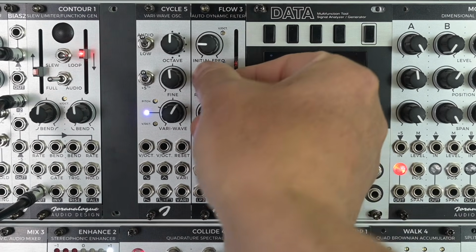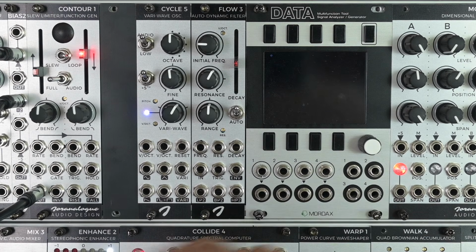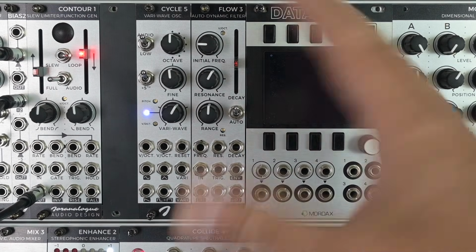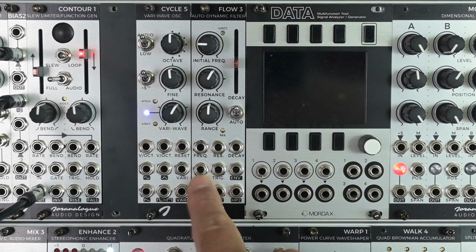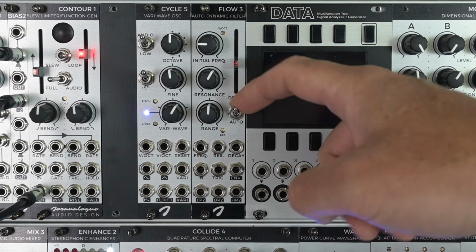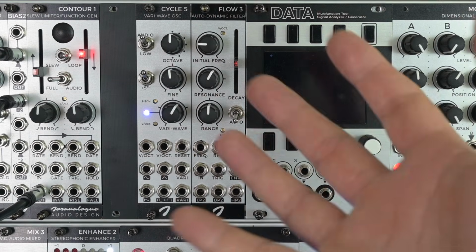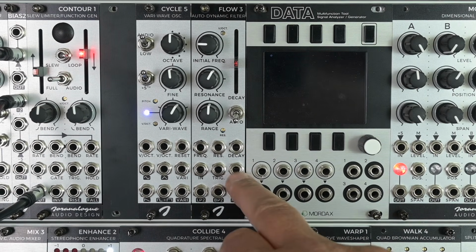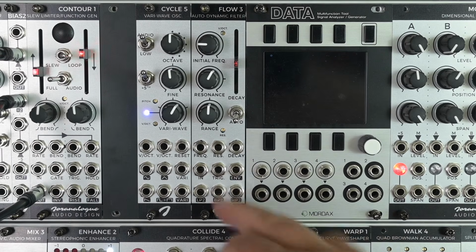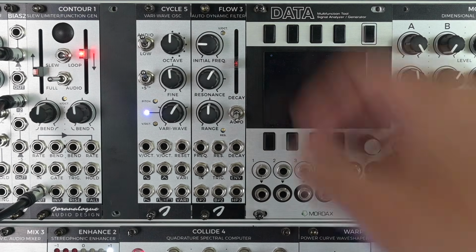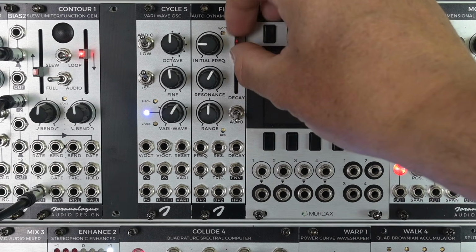The resonance goes into self-oscillation and you get 10 volt peak-to-peak quadrature sine waves from these three outputs. They are each 90 degrees out of phase with the previous one. There's also a built-in envelope follower for whatever you send into the signal input. You engage this envelope follower by switching this switch into the auto mode. Both the decay envelope and the CV signal generated by the envelope follower are available from this output here. This output is always a positive signal between 0 and 12 volts. You adjust the slew rate of this envelope follower with the slider as well.